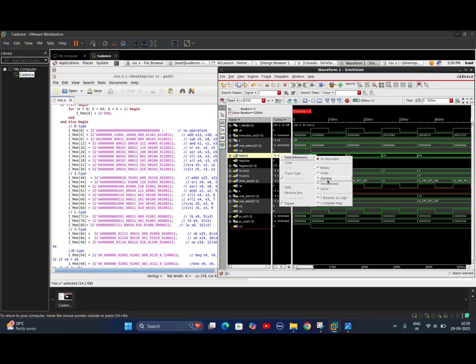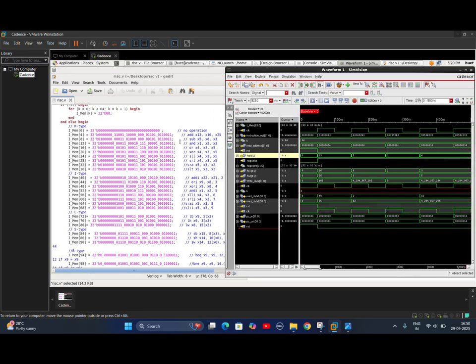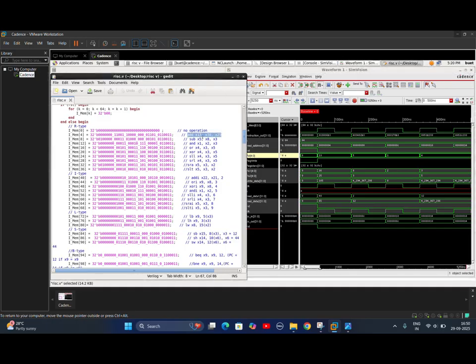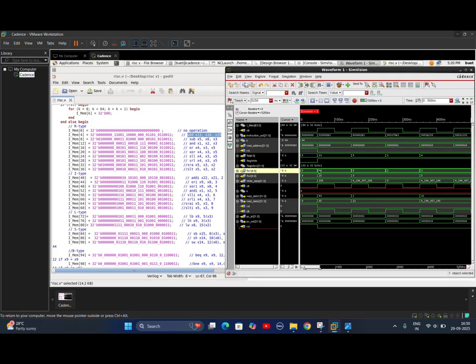Now we can see this is the instruction memory, where the first instruction is add x13, x16, x25. So we have to add x16 and x25. The register 1, rs1, is x16, so we can see the number 16 here, and rs2 is x25, this is the register number. So x16 and x25 have to be added and the sum stored into the register x13. We can see rd as the x13 register. So this is the instruction which we have been given.